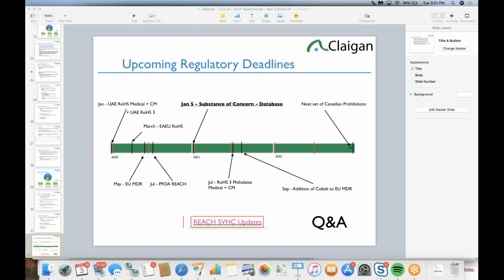What do we have to do if the REACH SVHC declaration or volume is under 1 ton? There's no tonnage basis for SCIP declaration. It is no tonnage. There is a notification requirement if you go over 1 ton and the use is not included in its dossier registration, which in almost every case is the lead in high temp solder, the lead in touchable parts, the lead in non-touchable parts. That's already covered in the REACH registrations. So you don't have to notify for them.